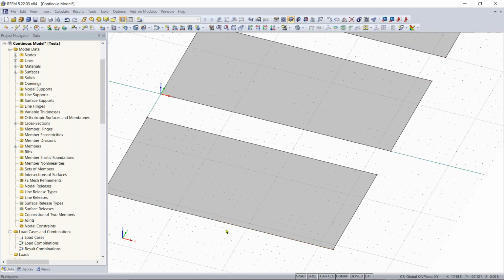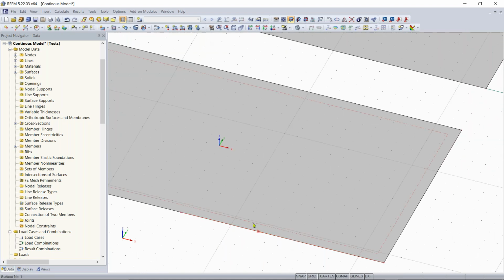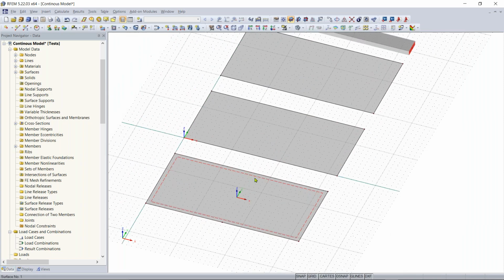So now you can see that this node has been created and the line was split at the middle. If you're wondering the orientation of the line and you're not sure what the start or end of the line is, you can see that when I hover my mouse over the line, there's an arrow here, and that'll show you the member start and member end of the line.